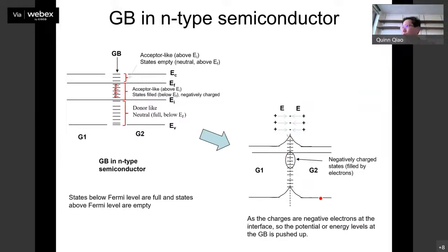Okay. The next thing you want to know is what happens to the electric field in between. Basically, there's this one junction. Here you have positive, here positive, because this is N-type and you lost these free electrons. You have only positive ions left, and then you have some negative charge trapped there. This trapped charge is why you form an electric field, from positive to the center, and then it changes direction, from negative to positive. So the electric field only exists inside, and outside they cancel themselves. That's what it means.